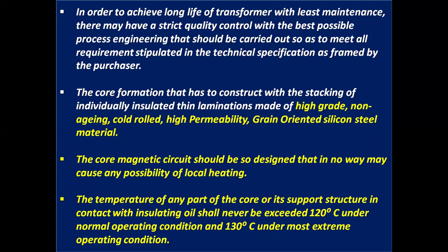The core formation has to be constructed with the stacking of individually insulated thin laminations of high-grade, non-aging, cold-rolled, high permeability, grain-oriented silicon steel material.